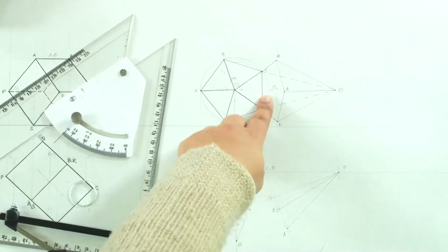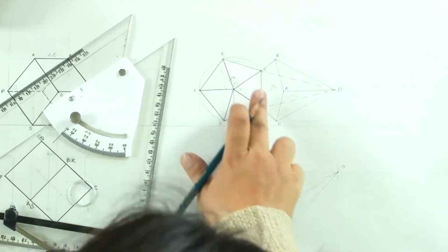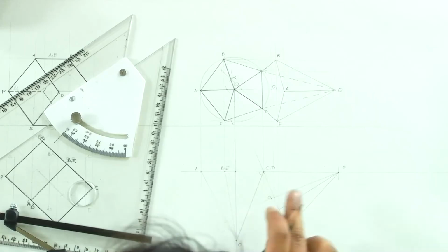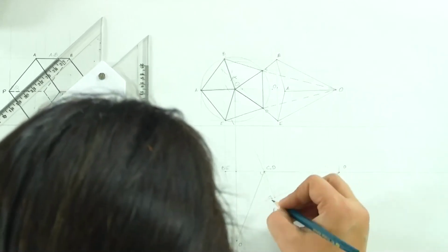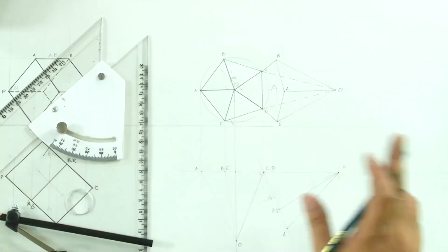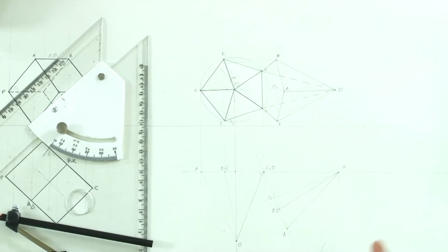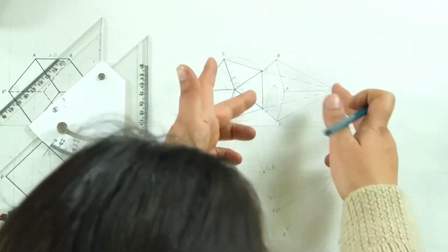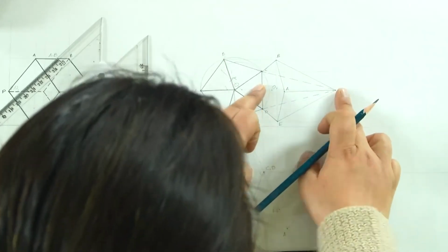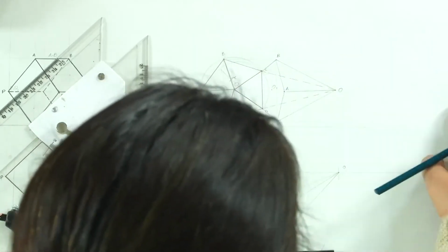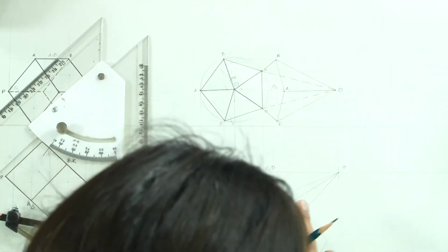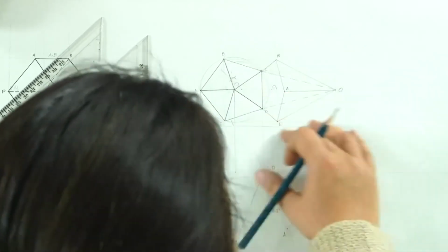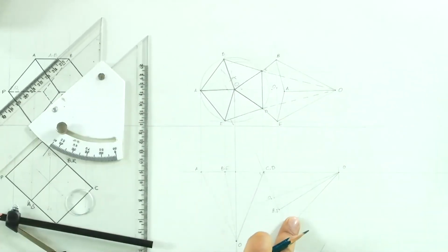So now if you see, this axis is still parallel to HP, but it is making a certain angle with VP, which is the angle of the cone. So the angle of cone is the angle which this is making, and so we see it slightly diminished here, but parallel to HP. So this is the current shape in front elevation and in the top view.